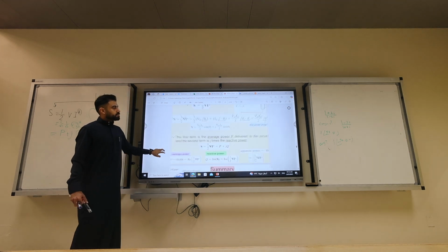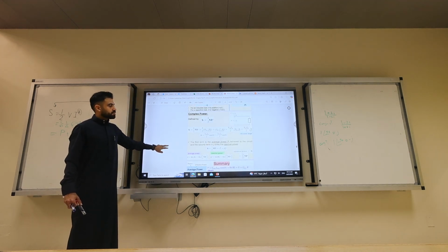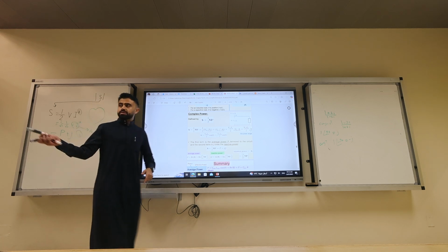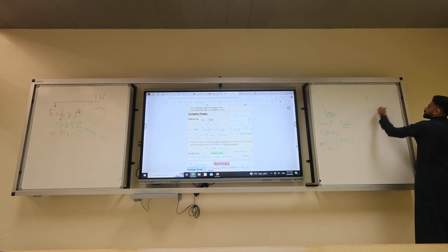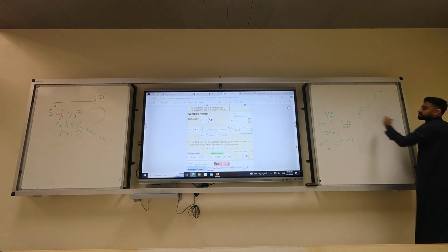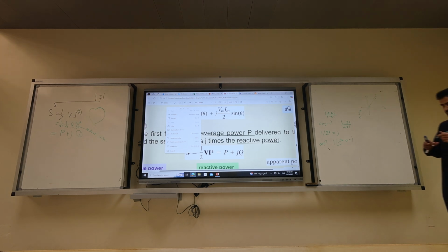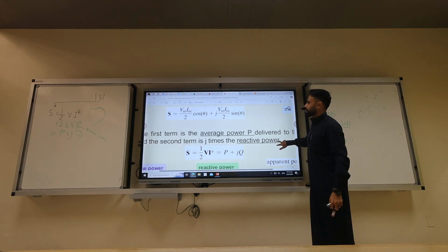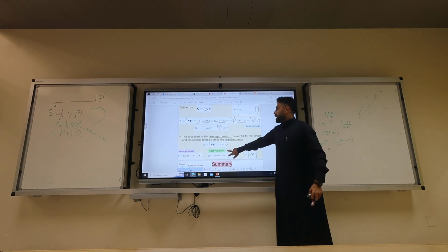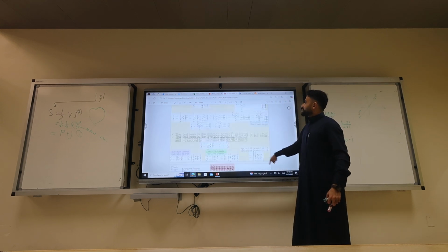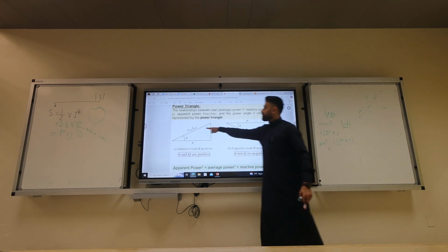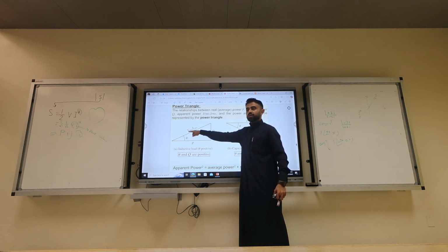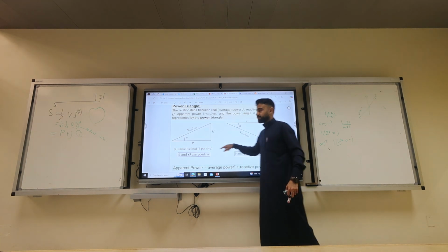Doctor? Yes. How do we represent the conjugate in phasors? Well, you just flip it 180 degrees. So if you have, for example, I here, I conjugate is this one. Get it? Keep in mind the apparent power absolute value of S, which is here, the previous slide, is nothing but VRMS times IRMS, or V over square root of 2 times I over square root of 2.